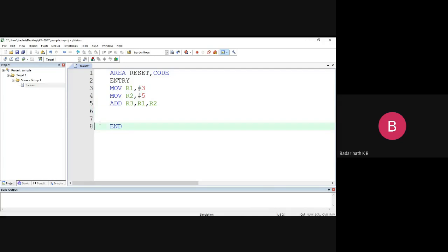One feature of any assembly language program is this. I was telling you in the case of an Arduino program also, after you run this program, where does the control go? There is no operating system in the ARM microcontroller board I'm talking about now. As soon as you finish your program execution, there is no place to return to. So once you finish your job, you should write a loop continuously. You should loop there only, an indefinite wait.